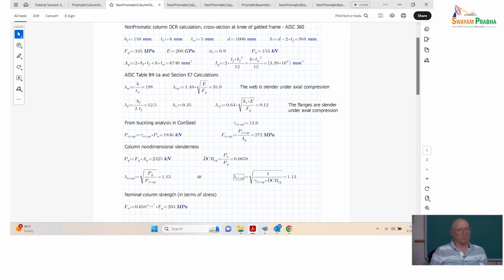And so generally, in Design Guide 25, it basically says, okay, here are several locations that you should check, and you look for whichever one is going to give you the largest PU over PPN. Well, it's just like your column design when you design multiple columns in a building. If you're checking all axial loads, you'd check them all and say, oh, that column over there is most critical, right? So you're just treating a non-prismatic member like multiple columns.